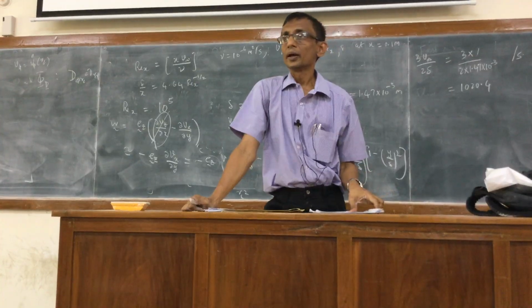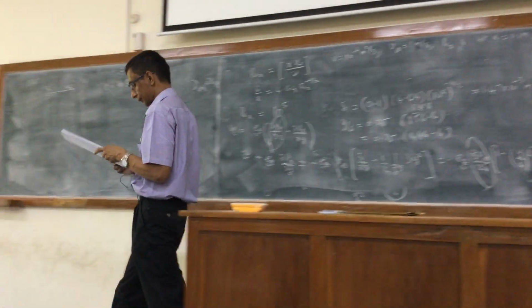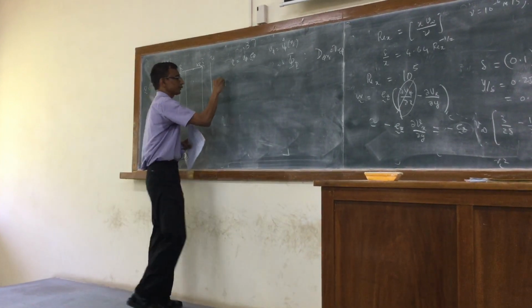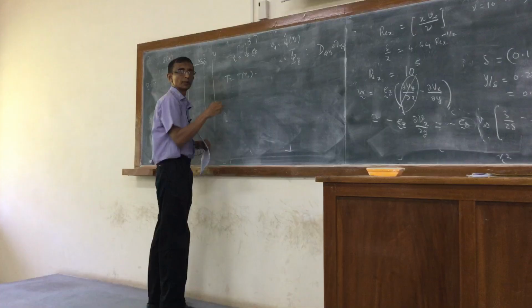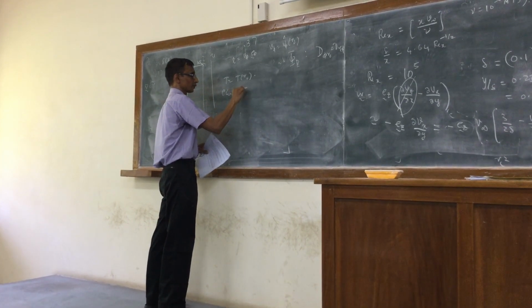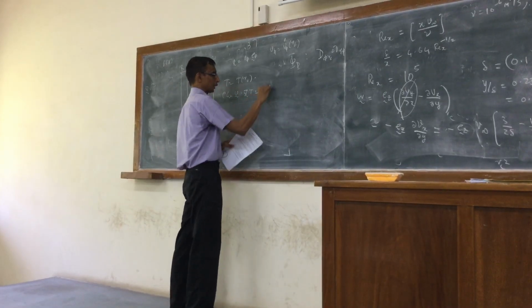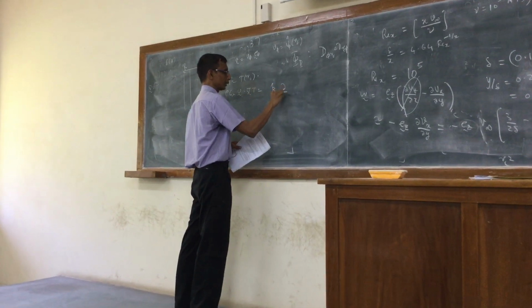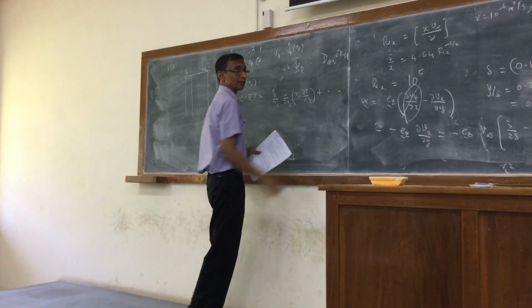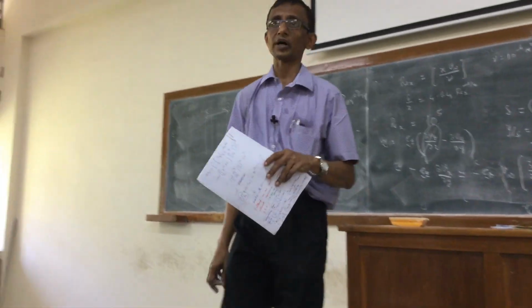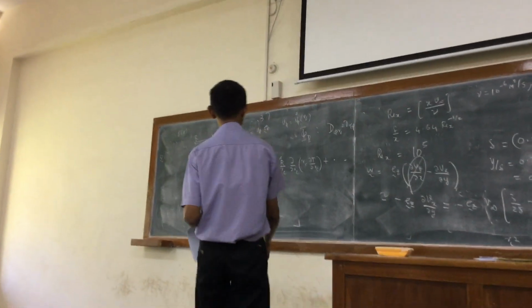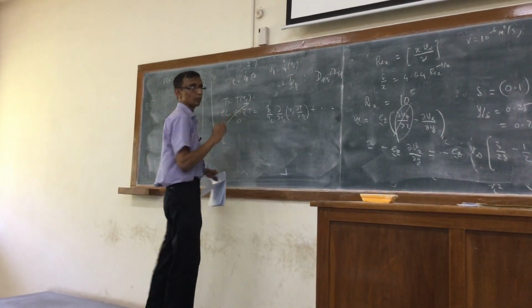And finally, the assumption that the axial conduction term can be neglected and you can consider T to be a function of r alone will considerably simplify the problem, because what you will find in this, you will get k by r d by dr, r dT by dr plus the viscous dissipation has been included. So here you will find that in this problem we can actually solve it using the viscous dissipation term, because this turns out to be 0.